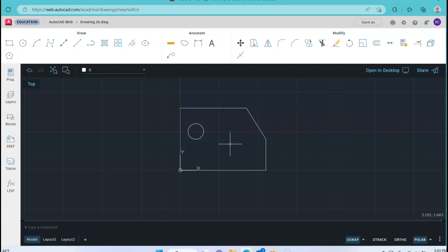Well, as I look at it, let's go ahead and go up to our circle drawing tool. My X is going to be at 3. I'm going to place my comma. My Y is at 1.5. So the positional coordinate of the center of this circle is X of 3, Y of 1.5.